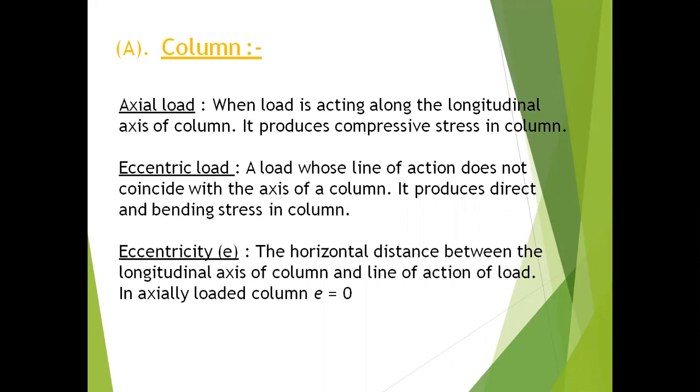Can we assure that as an engineer? No, it is impossible. Why? Because as we are constructing, there will be a lot of errors. Human errors, mechanical errors, design errors. There will be a lot of errors which make the column carry eccentric load instead of an axial load. Understood? Because it is not just a single column. On a column there is another column, on that column another column. Like that, there are around 10 columns at a single edge.